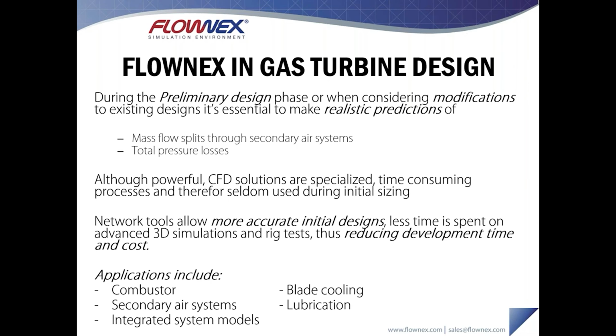And lastly, full integrated system models. We have the ability to model components like compressors or turbines at a very high level as well, using compressor charts or stage models. What it allows you to do is link your secondary air models or perhaps a lubrication model right to a full engine simulation, where you can adjust things like atmospheric boundary conditions and then have the boundary conditions of your subsystems calculated through the system components as well.